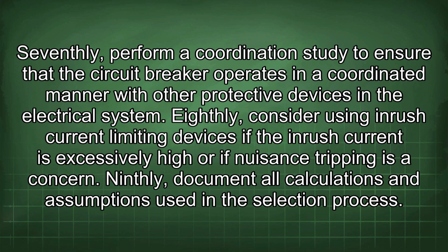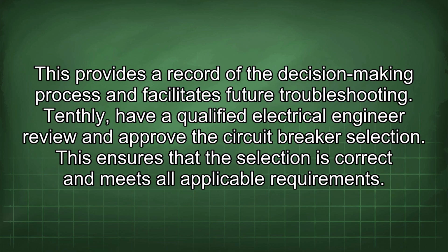Ninthly, document all calculations and assumptions used in the selection process. This provides a record of the decision-making process and facilitates future troubleshooting. Tenthly, have a qualified electrical engineer review and approve the circuit breaker selection. This ensures that the selection is correct and meets all applicable requirements.